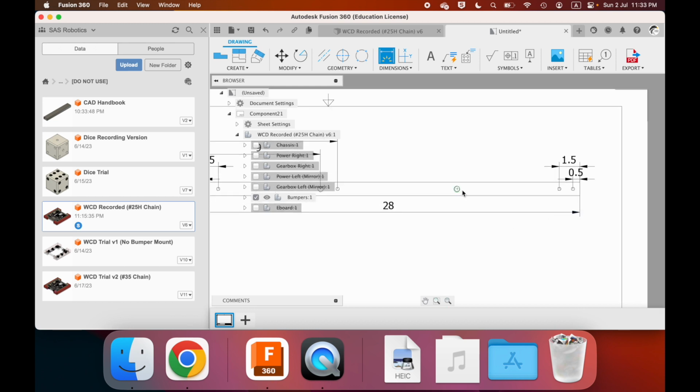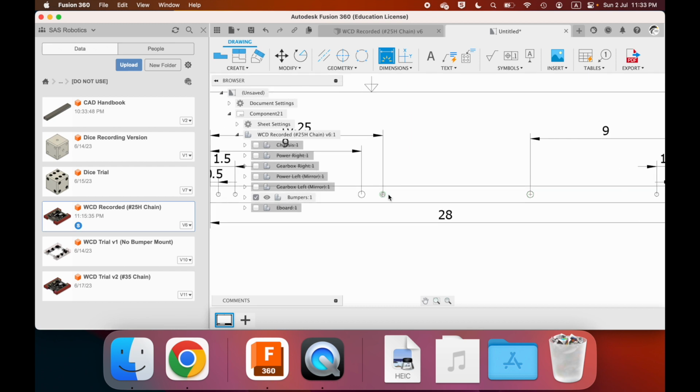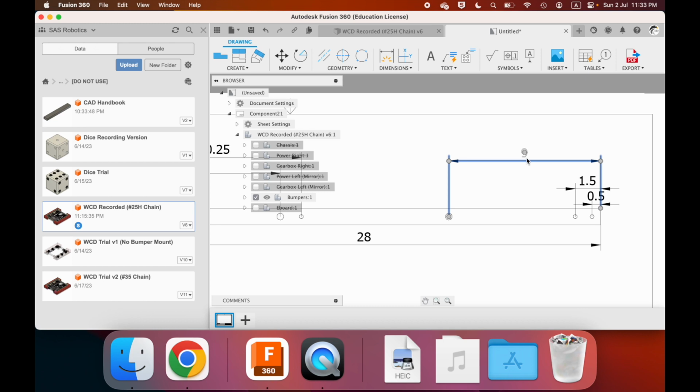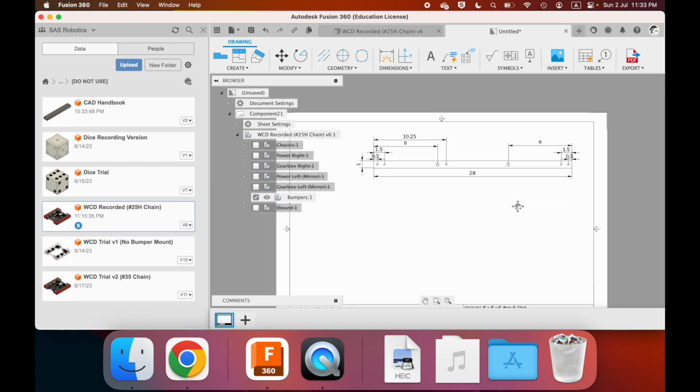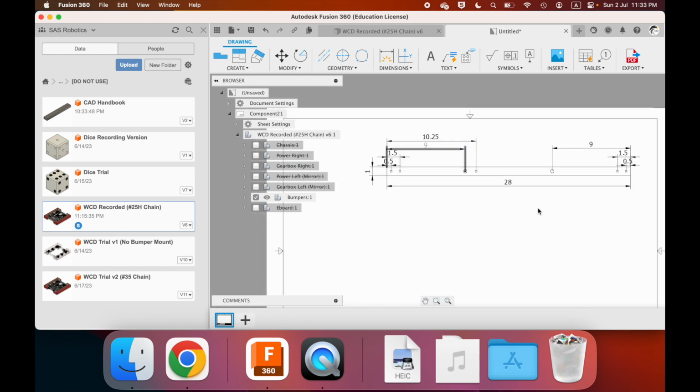Okay. If they accidentally cut this to 27 and 7/8, that's going to screw up all the dimensions, and this hole is not going to be the correct length from that hole. Maybe that affects your piece, maybe it doesn't. But unfortunately, we found that it's just too crowded to try to mark out all the dimensions coming off of one side. So this is just what it is, but you probably should be aware of that fabrication problem that can occur. Now, if mechanical is able to fabricate pieces well, then it's not an issue.